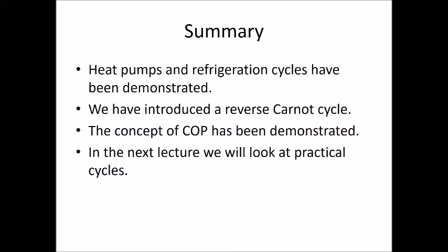So what we've covered in this lecture: you should now understand heat pumps and refrigeration cycles and how they work. You should understand the concept of the reverse Carnot cycle and what it means. You definitely need to understand this idea of coefficient of performance, how it differs from nominal forward Carnot cycle efficiency, and what the significance is, and this idea that as delta T gets larger, the COP gets lower, and in cases where the delta T is significantly high plus all our other losses, we may actually see less than 1 COP, and then the process itself starts to get drawn into question.